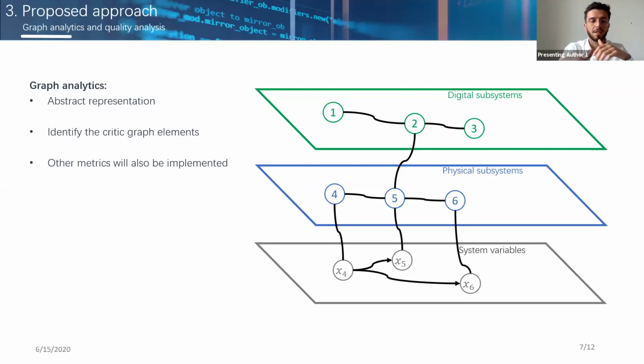Dependencies of any variable at any time can be defined as a state correlation model. We define two types of dependencies. Structural dependencies are when a variable deviation can cause the variation of the others. And operational dependencies are when a variable deviation is subject to the activation of specific values in other variables. These dependencies can be found out during the system design process. However, if that has not been done, a conventional control modification could be applied to modify one variable value at a time and observe the impact of that change on the other variables. A graph is built accordingly, with directed edges from the modified variable to the altered ones.